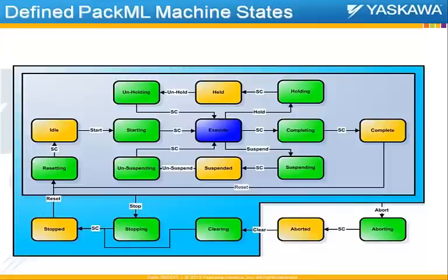And PackML already defines that in our template, which I'll show you in a little bit here. It already handles those exact transitions and forces you to go through this specific flow. There are only two where you can jump out. A stop transition will jump directly from anywhere to the stopping state, and abort, of course, will jump anywhere into an aborting state.